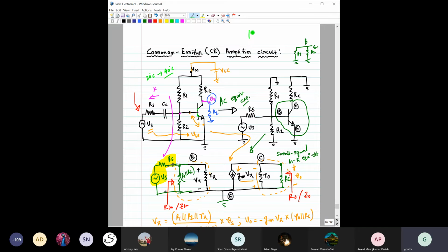If you consider this an NPN, these are the depletion layers that are there, and when the current flows, even though these regions are heavily doped, the base region is not that heavily doped, and the collector is also not that heavily doped. So this region will offer some resistance, right? So if the current increases, then more voltage will drop across this, meaning the I squared R drop. More drop will occur across this transistor.